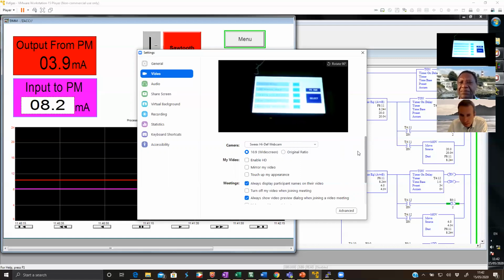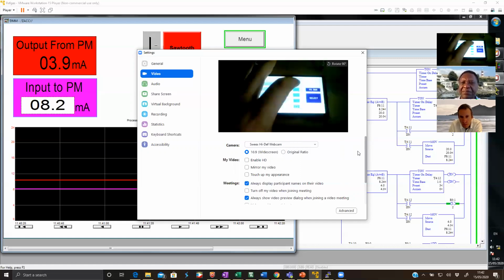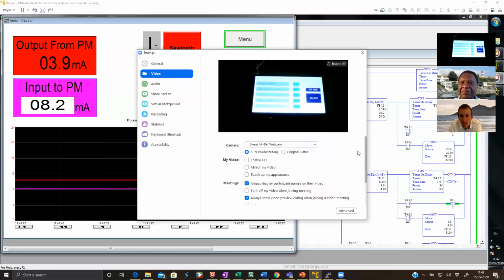That's why I changed very quickly to indirect addressing. Instead of needing 10 pages, I've now just got 1 page. If I click information, it calls the information page. It prints out the shell of the page and then populates it with information. So definitely the touch screen and getting everything to work inside the screen, trying to make it a good machine-to-user interface, was the most challenging part.